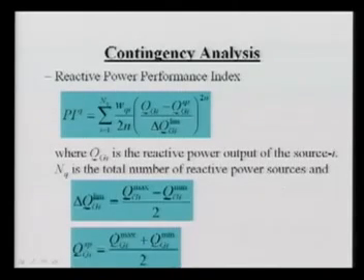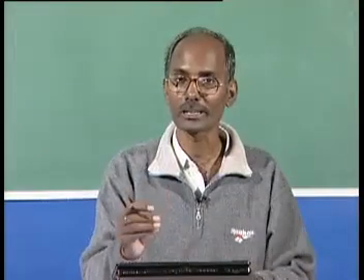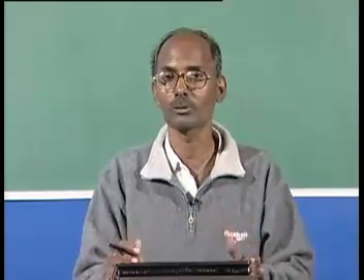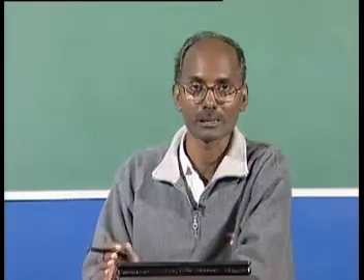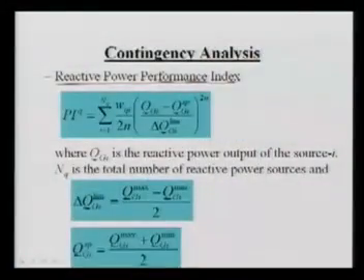Similarly, some people say that the voltage performance index may not be adequate. Then they define another, a reactive power performance index, similar to the real power flow performance index. Basically, this reactive power performance index is about reactive power generation, meaning how much reactive power you are putting into the system, how much requirement is there, and that gives the relative criticality of the system. Similar to PIV, here we are adding NQ, meaning how many sources you have in your system, meaning how much reactive power.